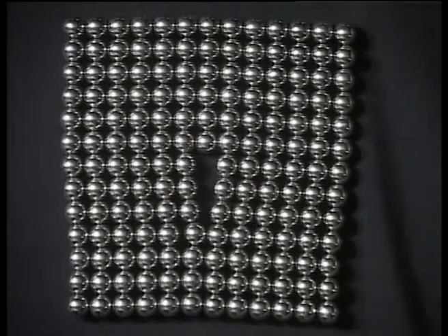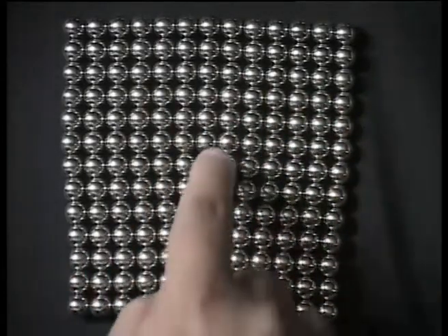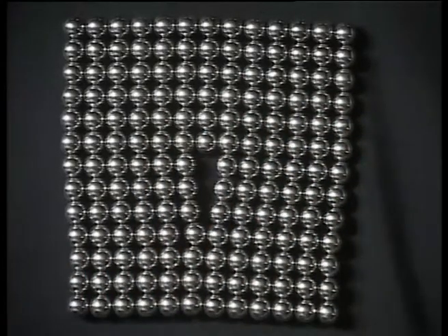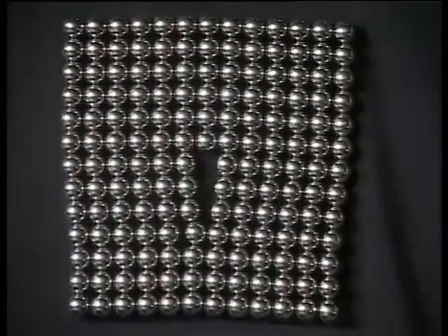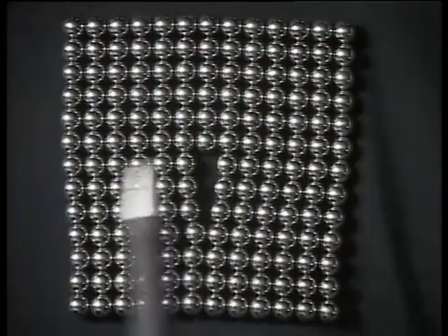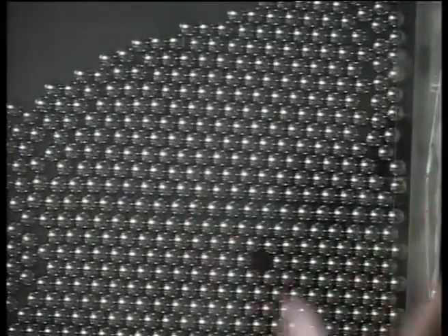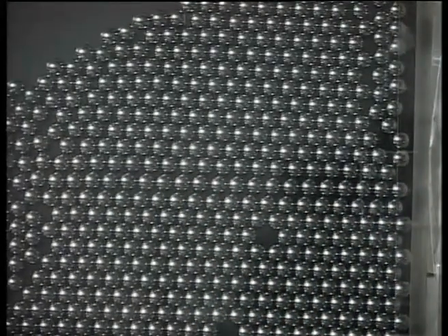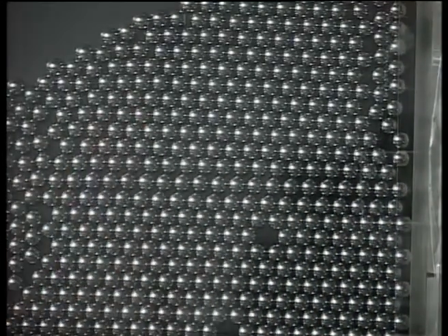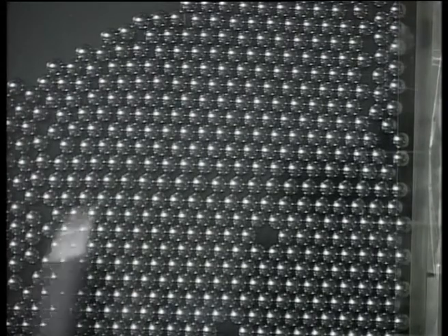Of course, in 2 dimensions this is just a 2 dimensional crystal, therefore, this is a dislocation point, but in 3 dimensions, suppose I had a crystal like this pervading many layers below, that would be a dislocation line. So, with these small toy models I can try to understand some of these simple crystals, and many of you can make these kinds of toy models at home with these cycle ball bearing balls, and then try to understand some of these structures which form when you try to make a crystalline array.